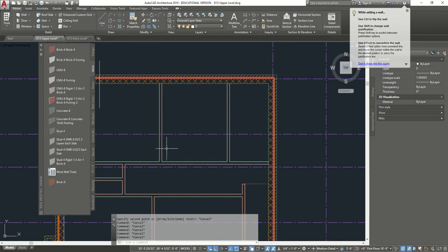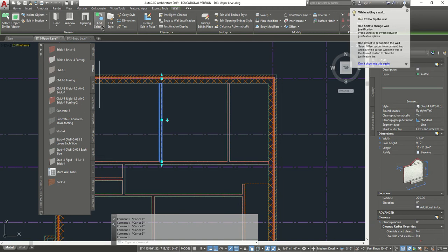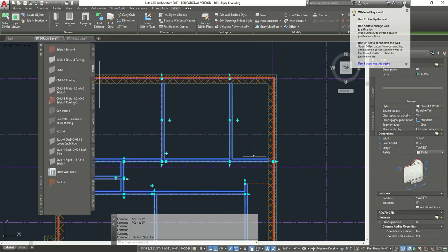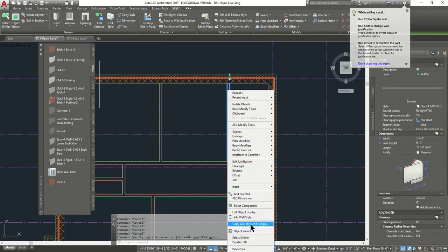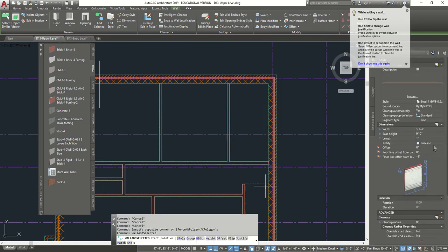And then from here now, we're doing one more wall. A lot of walls we're adding here. Let's go select similar. This time let's make sure we're going, where is it? Justify, we're going to go towards the right, I think this time makes more sense. And oh, I just changed all the walls. Hold on. Grab this wall. My bad. And then we're going to go to add selected. We're going to change it to the right.